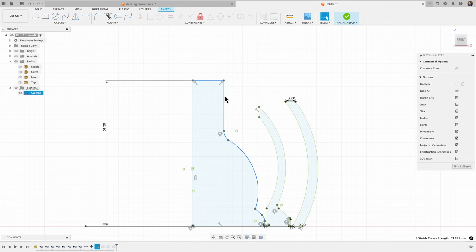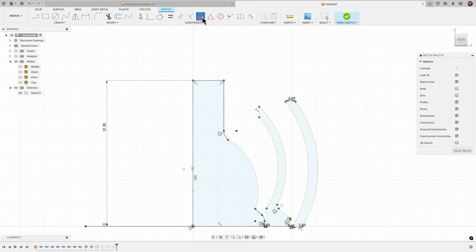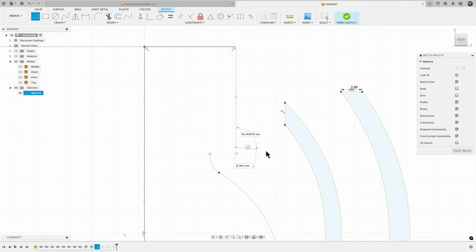I'm going to double click this section here and go to unfix. I'm going to delete these lines here, and let's look at recreating this. So maybe take this, go across roughly 8 millimeters or so. I'm going to go down about 10, and then here's the part where I'm going to go in with the hat. I'm going to go right, down, and then left. Click the check mark. I want something like that.